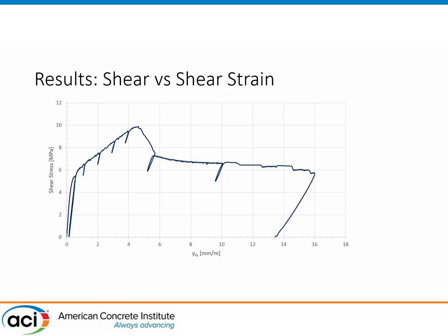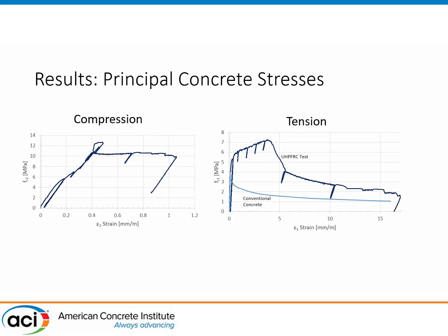Once we have these results, we're now able to look at the principal directions, principal compression direction, principal tension direction. The strain showed us that it wasn't perfectly horizontal and vertical. There was some twisting of a few degrees, but that's not important. We're able then to calculate what we have as the principal compression behavior and the principal tension behavior. Now, the principal compression behavior is the compression stress versus the compressive strain. Don't worry about the wiggle on top. We'll talk about that in a second.